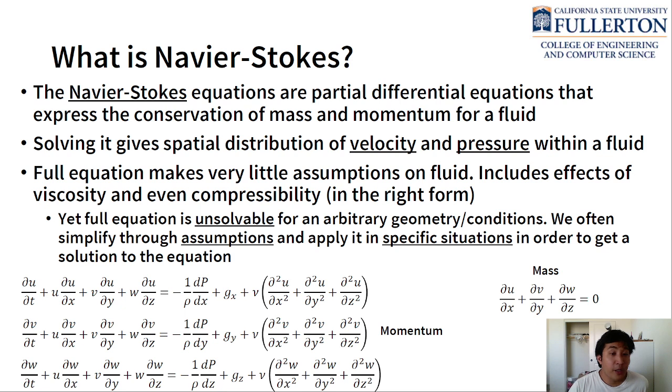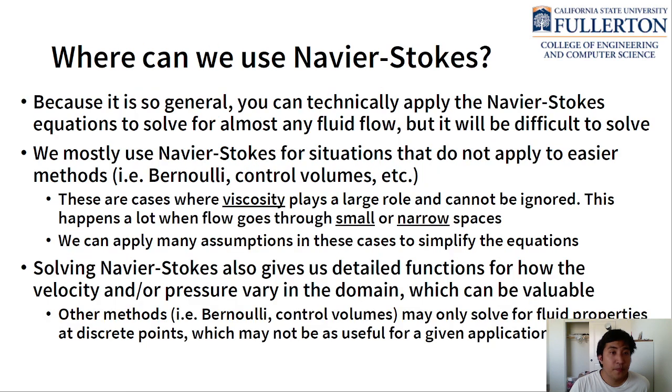Okay. And so the equations that I'm showing you here are kind of a specialized version for Navier-Stokes for an incompressible fluid. But for most of the fluids that you deal with, unless you're working in aerospace, these equations are going to work just fine. And that's the one that we mostly focus on in an introductory fluids class like this one. Okay, so now let's ask, when can we use Navier-Stokes? And so, the real answer to this is actually you can technically almost use it anywhere because it's so general. The only issue is that you just won't be able to solve it unless you have very, very powerful computers.